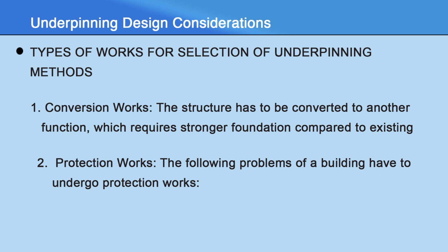The existing foundation is not strong or stable. Nearby excavation would affect the soil that supports existing footing. Stabilization of foundation soil to resist against the natural climatic, and requirement of basement below an already existing structure.